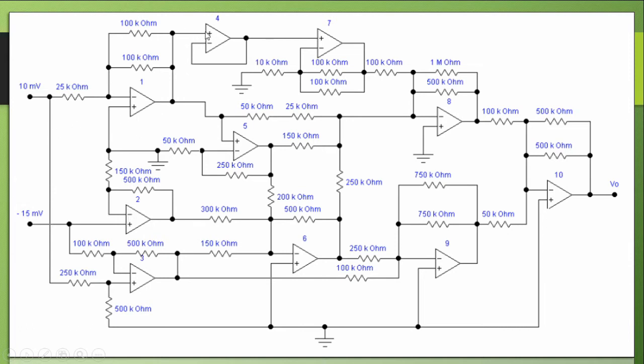And we should not be bothered by op-amp 4 and other circuits connected to the op-amp, because we know that for an ideal op-amp, the current here is 0, right? So if the current here is 0, then basically this is just an open circuit. We can consider this an open circuit.